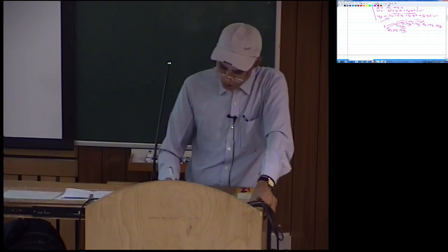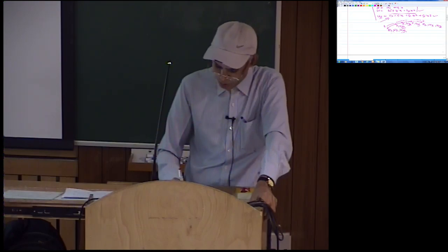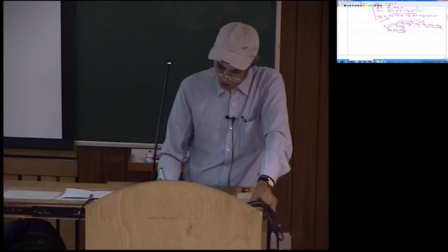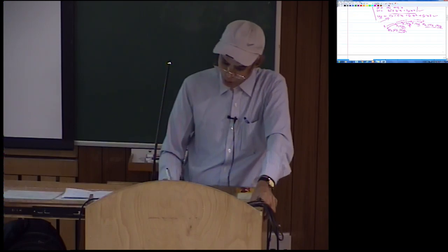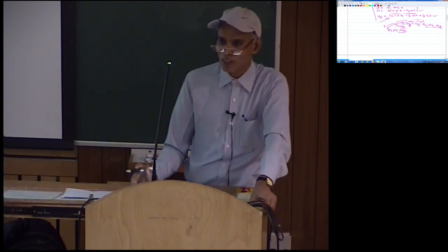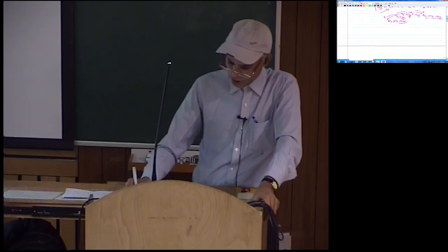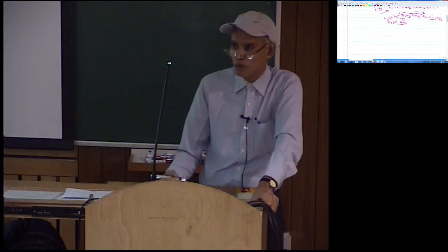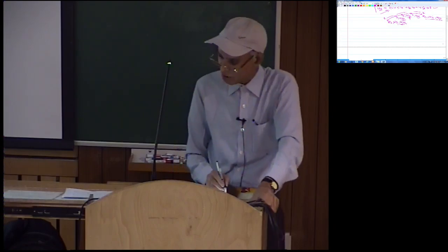So the element is obviously, as you see, different nodes having different degrees of freedom. At the end nodes I've got 3 degrees of freedom, then we have one node at the center which has only 1 degree of freedom, that is W, and we have 2 more nodes which have only the degree of freedom U0. So it's more complex of course, and usually you don't find such elements in software. If you're developing your own code, you can obviously do that and study the problem.